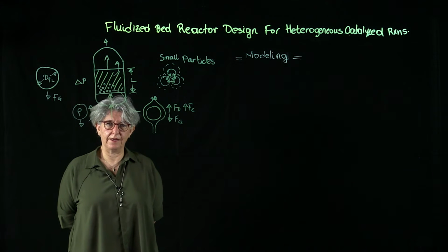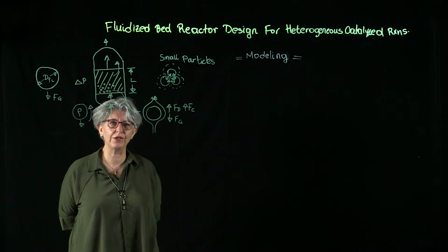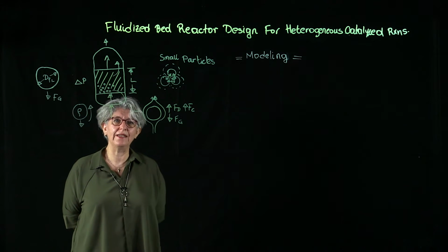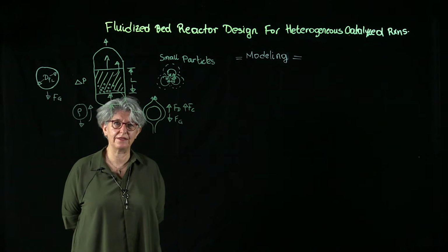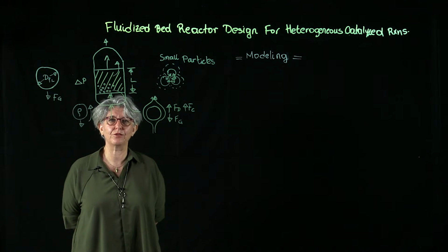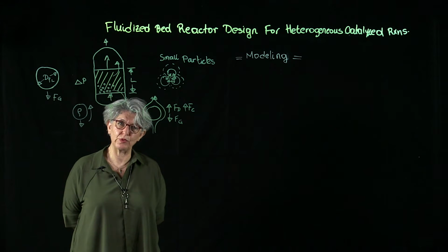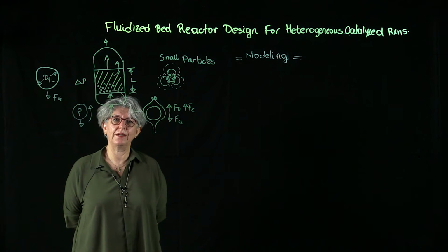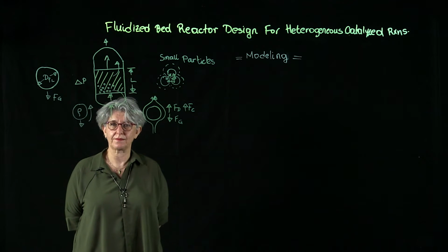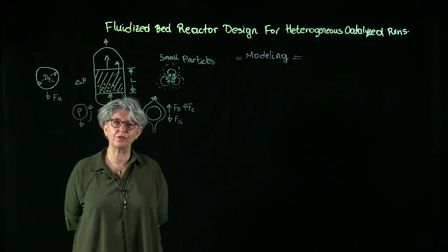In as complex a domain as a fluidized bed, we need to make certain approximations in order to have a reasonably simple model still containing the complexities of the problem. In an accurate, rigorous model of a fluidized bed, we have to take momentum, energy, and species conservation equations into consideration for a fully rigorous solution of the reaction problem in a fluidized bed.